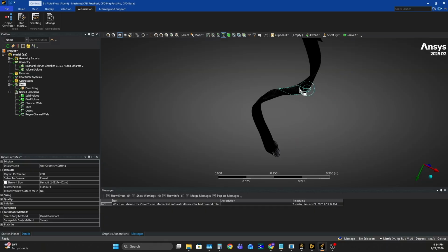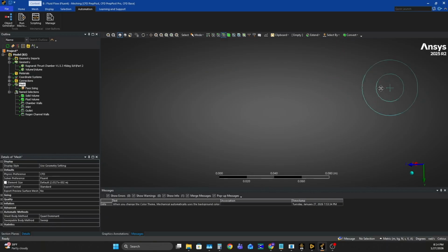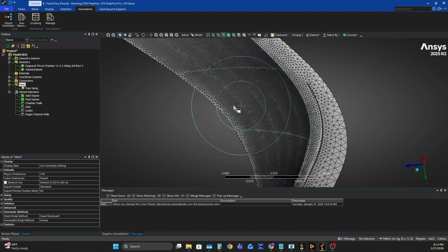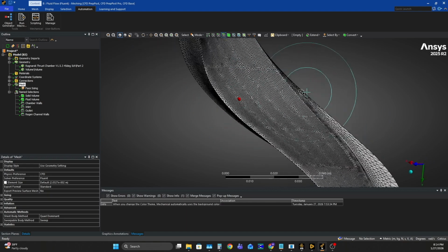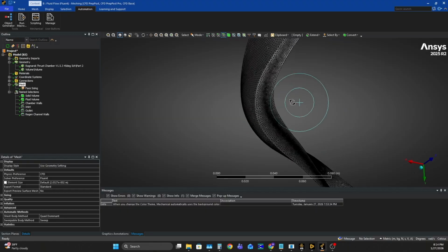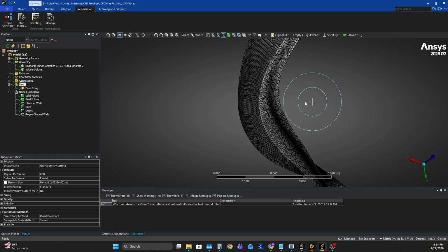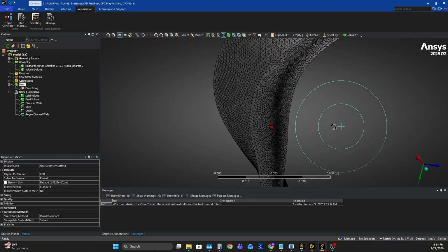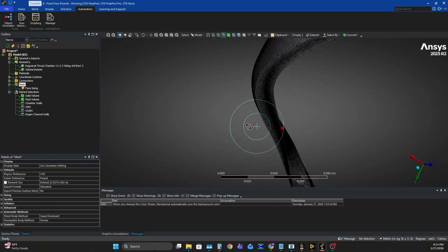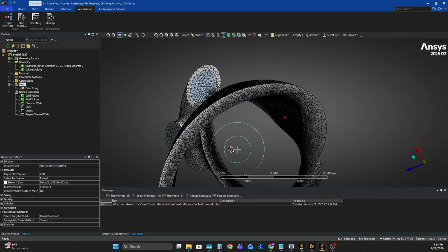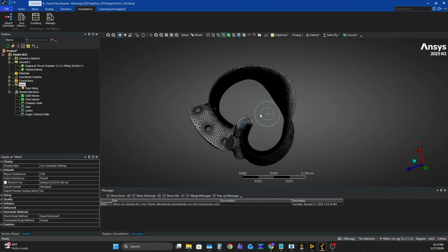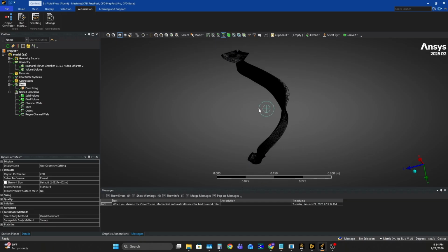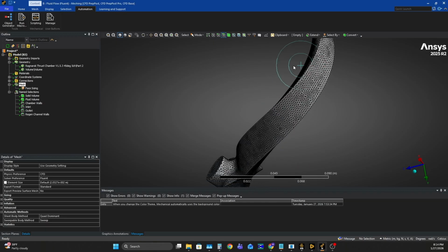But yeah, this mesh works. Sometimes if you generate this mesh and you see that the solid portion is very, very coarse, likely something's messed up. I would not continue. It will not work. It's possible that part of your regen channel is poking out through the mesh. And if that happens, you may have to go back to your CAD model and make sure that no part of your regen channel that you're modeling is poking out of your solid body.